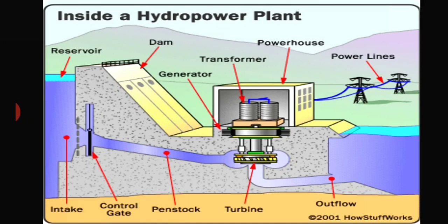Now we can look into a hydropower plant where we have a hydraulic turbine. We build dams across rivers to keep water in a reservoir, keeping water at a particular height. Height is a major factor, because when you keep water at a high head in a reservoir, the total energy of the water will be high, or simply, the potential energy mgh of the water in a reservoir will be more.